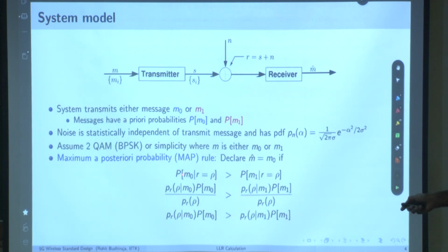Right. So we use Bayes rule to move from here to here. You should also notice this is capital P. This is discrete probability, because messages are discrete. Now what is this, from here to here? When I write small p, this is rho. This is a received signal, and what is happening over here? We are adding noise, Gaussian noise.